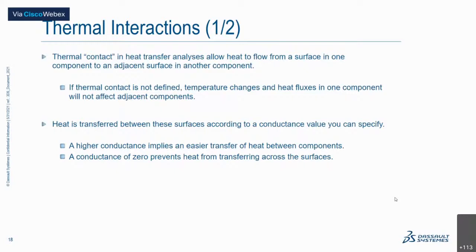If thermal contact is not defined, then your temperature changes and heat flux won't be affecting the other component, and your simulation results won't be that accurate as well. The other thing to note is, the higher the conductance value, the easier it is to transfer heat between the components. And if a conductance value of 0 is defined, then it prevents any heat transfer between the components. So just like your structural interactions, we have to define thermal interactions too while doing a thermal simulation.